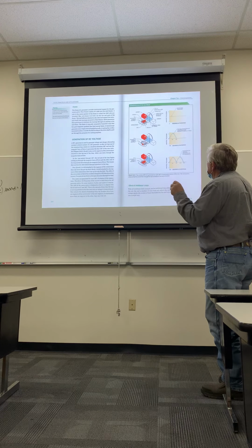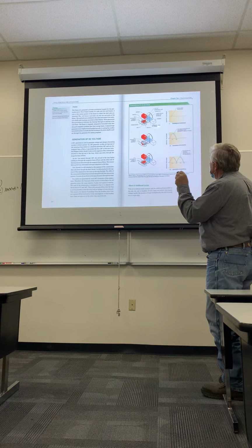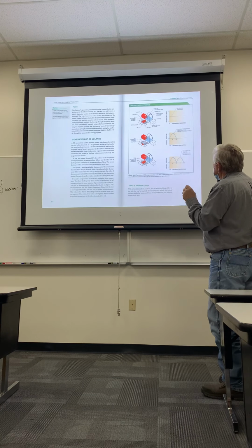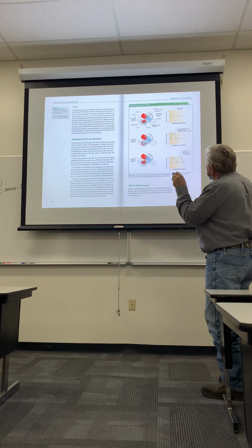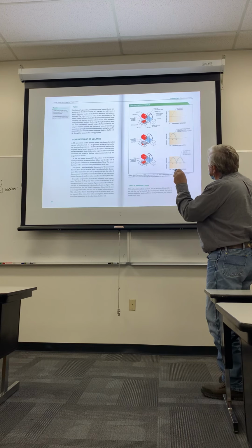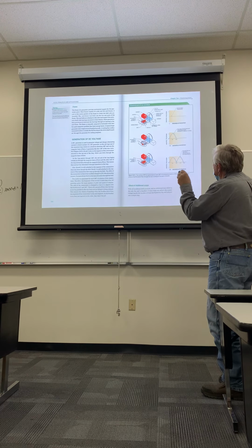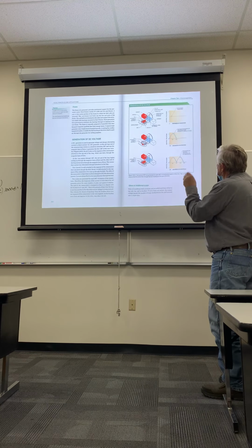Okay, so we get this set up now. Have a nice magnet here. Have lines of magnetic flux going back and forth. We have one conductor, and they have made a red side and a white side for you, and they've set up a sine wave over here for you to see how this is produced. When this is turned, so we bring power from somewhere, and we turn this, it pushes this conductor through these lines of flux. So now notice here, the red one is up at the top. Now we've gone 180 degrees, so now the red one's at the bottom. So we've made 1/2 of a turn, and notice that it's produced 1/2 of the sine wave.